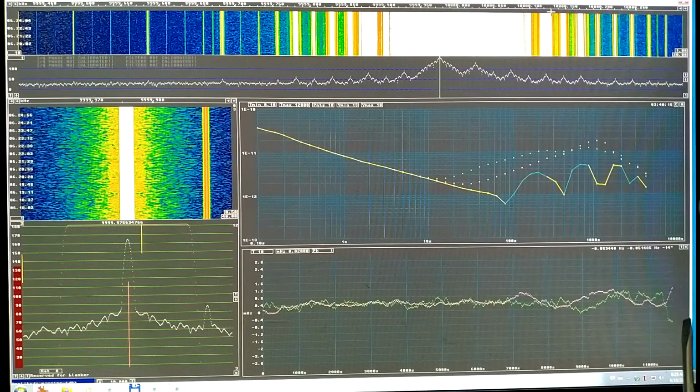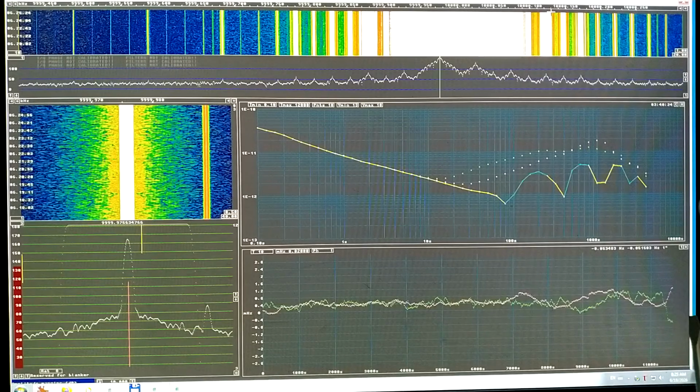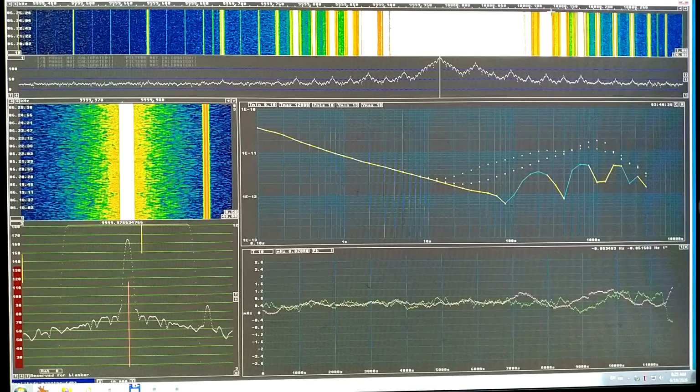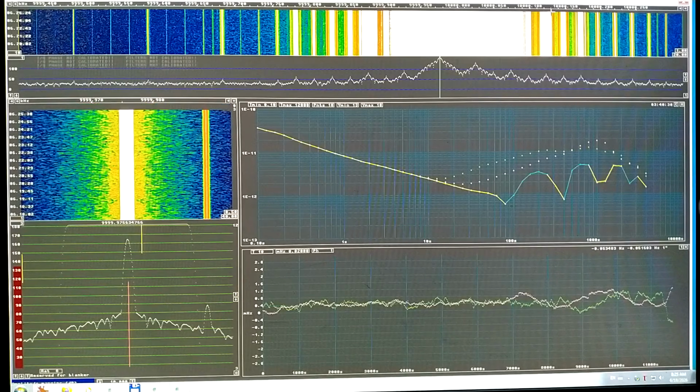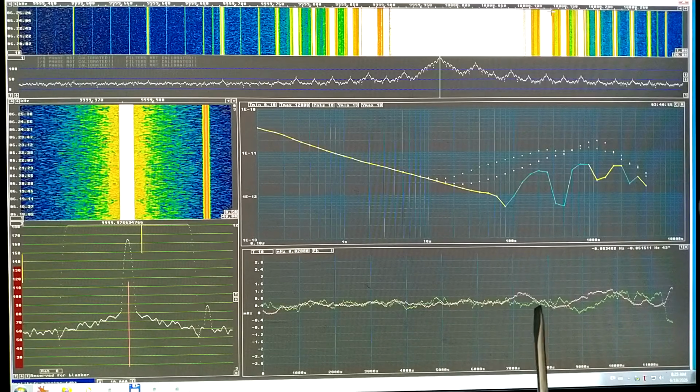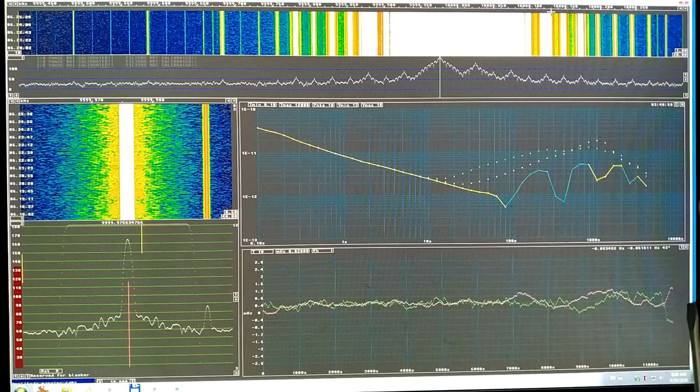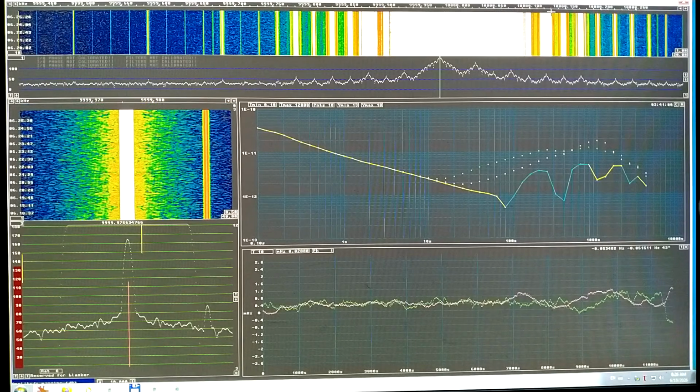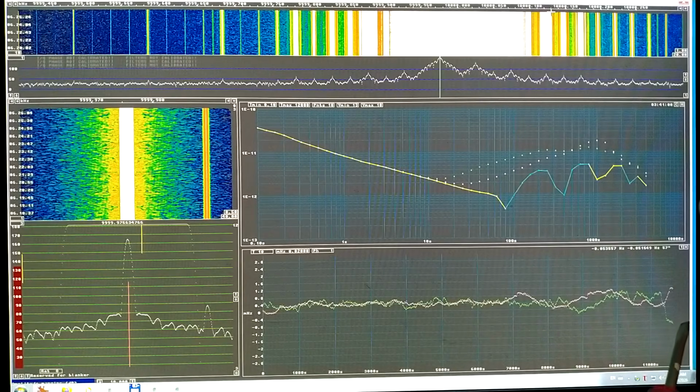Well, this is clearly a more dramatic change than what I had here, because I stepped inside here. It seems that the temperature coefficient is in opposite directions for the two oscillators I have. Well, this doesn't really matter. This is noise very close to the carrier, and I'm mainly interested in the phase noise and amplitude noise down to about 0.1 hertz, and then this is perfectly okay.